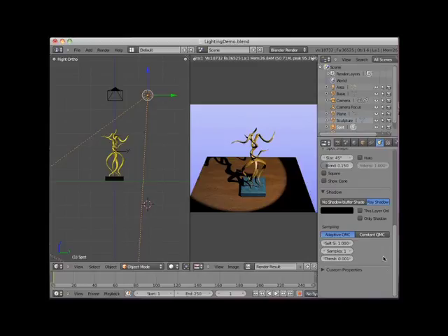The adaptive QMC method is used to calculate shadow values in a slightly less uniform and distributed way. This method results in a good calculation of shadow value, but not as good as the constant QMC. The advantage of using adaptive QMC is that it is generally much quicker. With both the adaptive and constant QMC methods, the higher the sample number, the softer and more transparent the shadow. I will choose the constant QMC method. With the soft size set to 1, I will set the samples to 3, and then render the scene. The sculpture now casts a very soft and fairly uniform shadow.